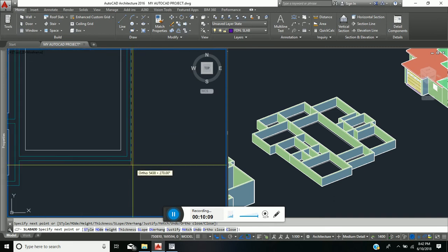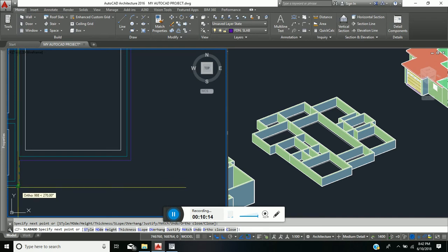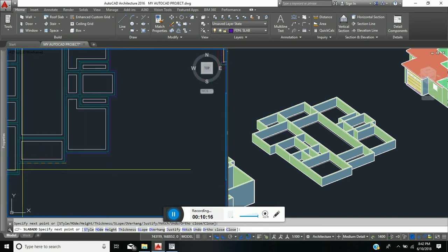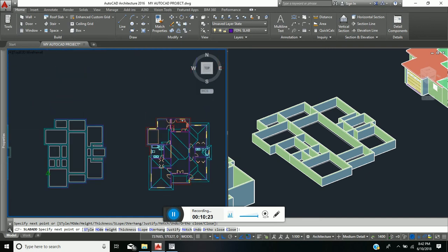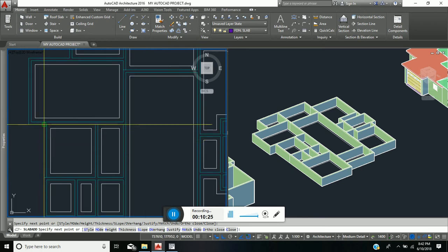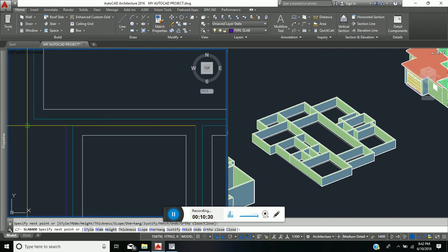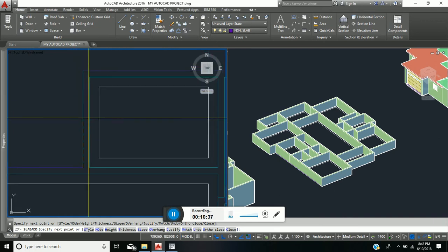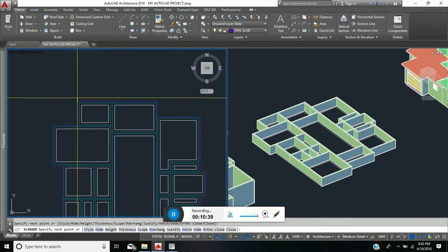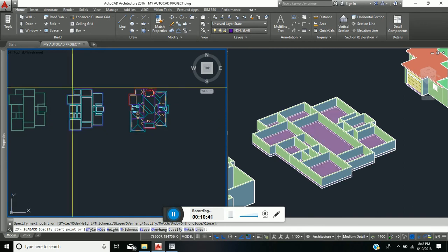I'm being careful to select my corners properly as I pick around the building. You are not seeing the overhang just now, but when we get to the end and give that enter, you will realize that an overhang would have been included. Sometimes you have to zoom in closely to ensure you are hitting the real spot.